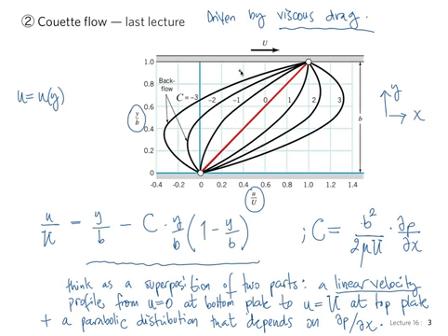Because basically the top plate is just dragging the fluid along because of the no-slip boundary condition. The top plate is moving. And so I'm using the words rather loosely here. I don't mean drag as the force of drag that we used to talk about in the sense of flow around immersed bodies or anything like that. But it's a viscous drag. It's a wall shear that causes the fluid to stick to that wall and want to flow with it, right? And causes the fluid to stick to the bottom wall and want to be stationary with it.